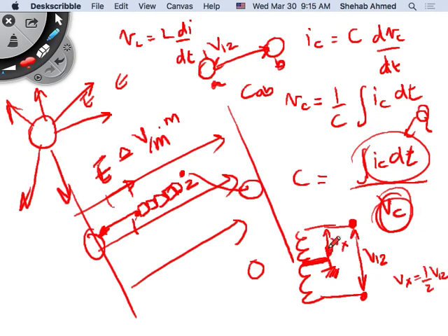So then I can calculate now the capacitance. If I calculated the capacitance between two lines, I can calculate the capacitance between one line and ground this way, by looking at half the voltage. Half the voltage will give me twice the capacitance, right? V12 is equal to X, for example. Now this X is X over 2. Bring this 2 up here. So basically I will end up with double the capacitance. So if I calculate the capacitance between two conductors, take that and multiply by 2, it's the capacitance between conductor and ground. And that is my interest.